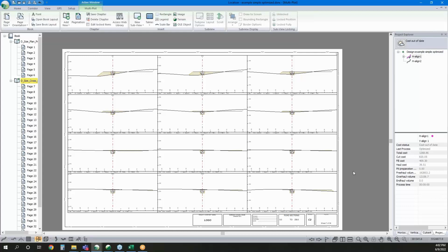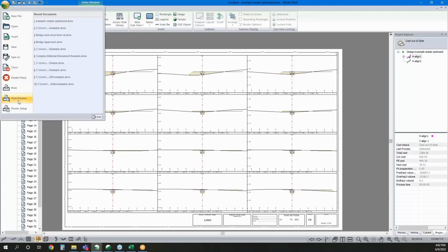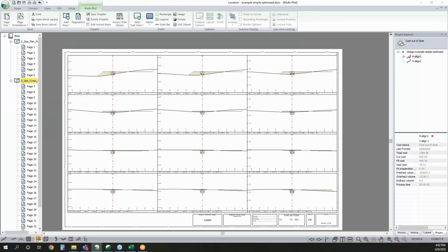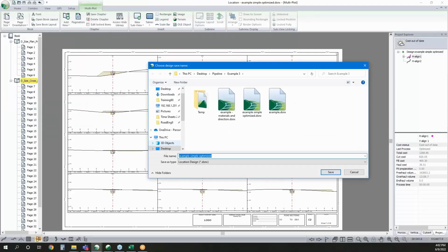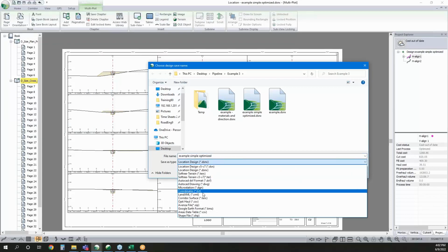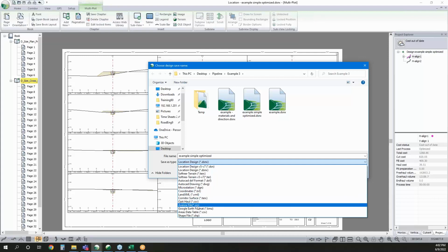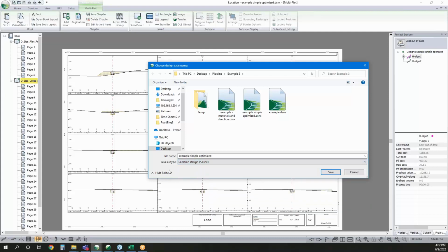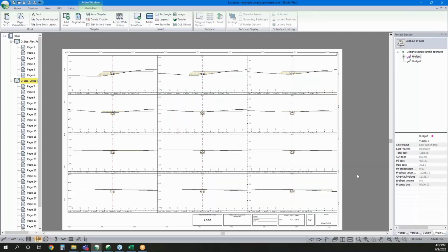A couple things that I'll just add that make it worthwhile to mention. Of course, all this information is useful to have for construction. So if I wanted to take this document and have a georeferenced document that I can use in the field, I can save it as an Avenza file. I could plot it to a PDF, or share it to a shapefile if I need to share it with the GIS department. So sharing that information is pretty straightforward.